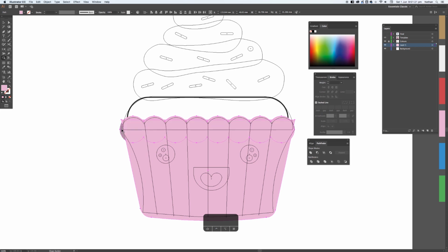As you move your mouse over different parts of the two objects, you'll see that they become hashed or greyed out. These are the areas that you're about to edit. Also, you'll notice when you press the Shift key, your cursor turns from a plus to a minus. The minus obviously means you can subtract the areas that are greyed out. And that's what we're going to do, just going around cleaning out the overlapping areas.